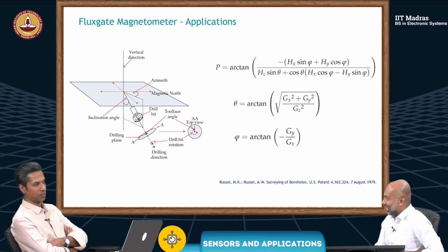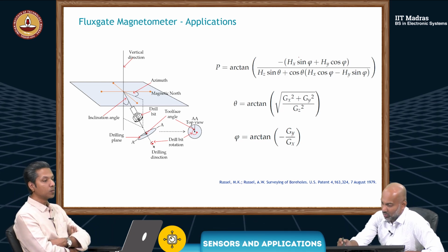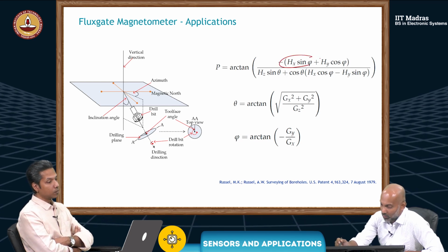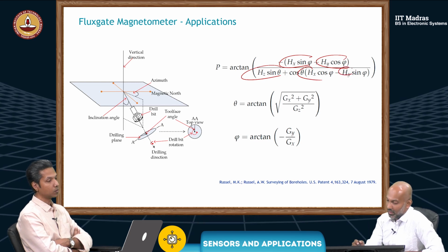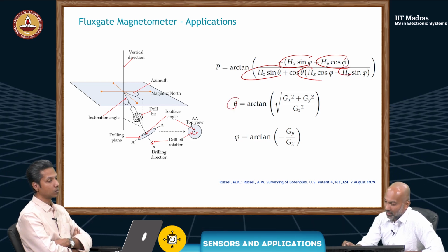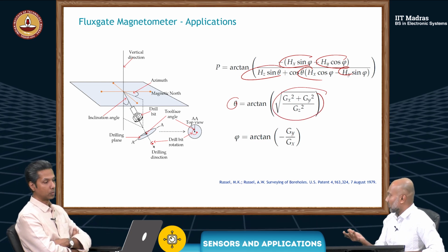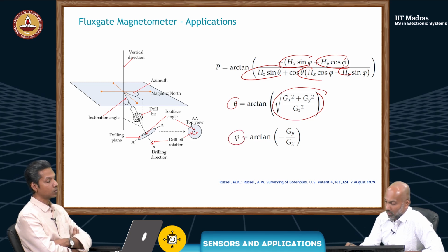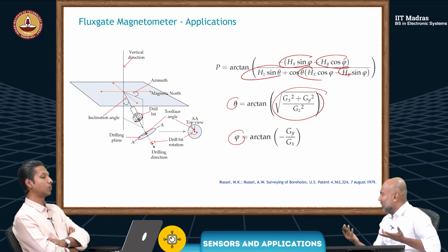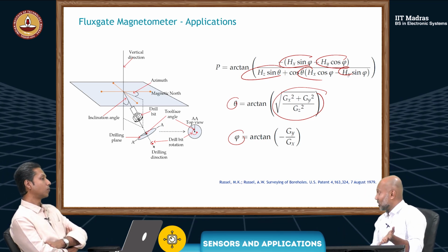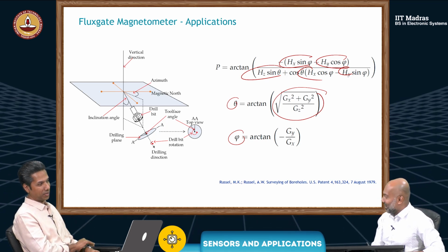Again, this is just an equation. Your fluxgate magnetometers will help you measure these, your HXs, HYs. Theta here is obtained with your gravitational components by the accelerometer, and so is phi. But X, Y, and Z is found by the fluxgate. So again, another example of a niche application for fluxgates. It's actually for navigation, but underground, because you cannot see.